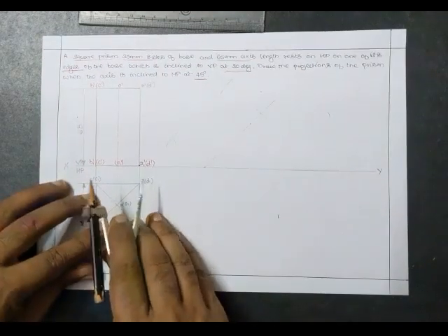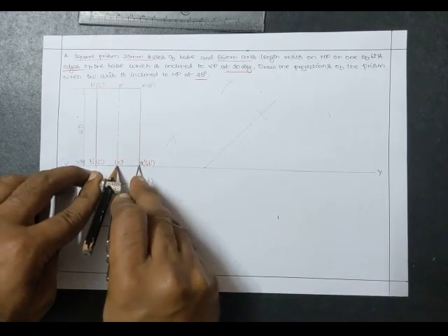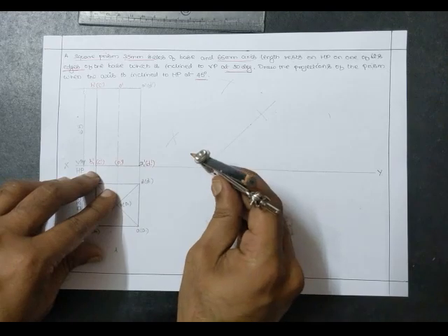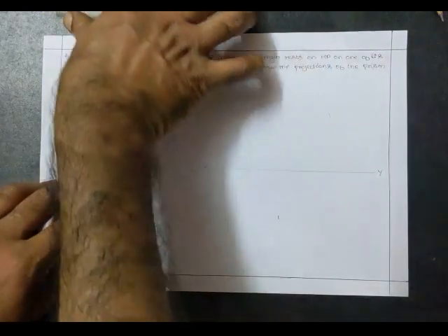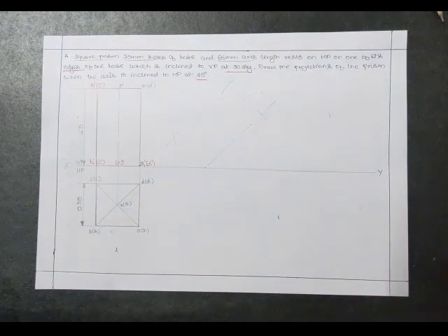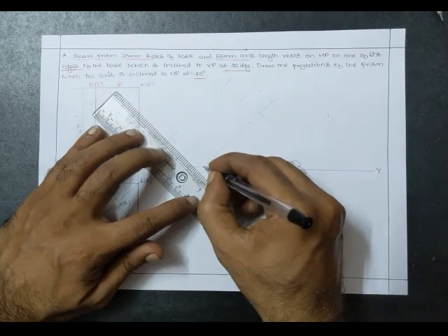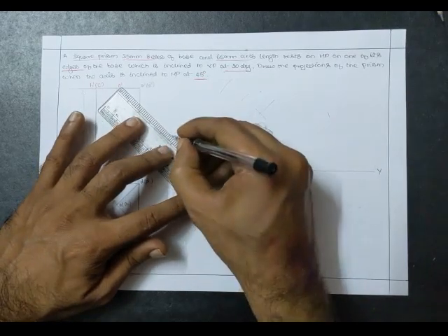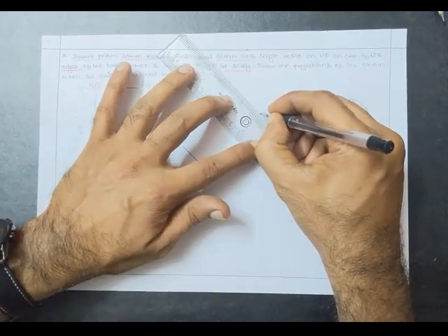Once you get that, you measure the parallel distance of the axis, because the inclination is given with respect to the axis, so it is our job to show the axis. Now every point is marked. Next, you have to draw the projections. Since it's appearing light, I'm going to change the pen. Let me darken the visible edges. I'm just transferring the first position to the second position, nothing else.